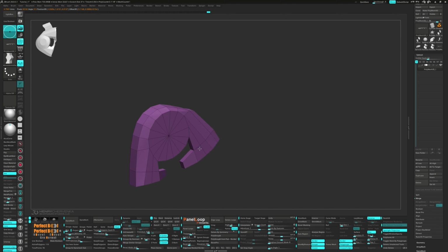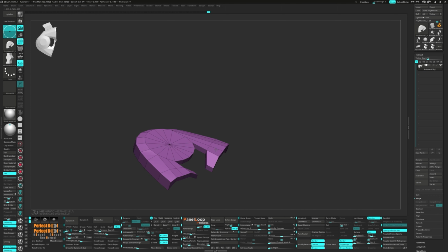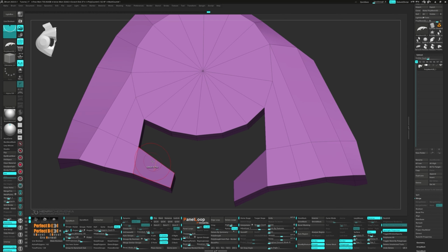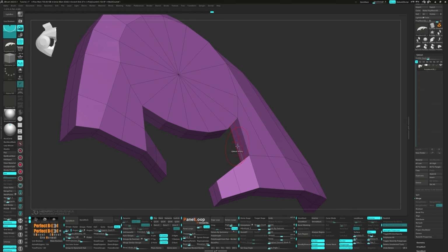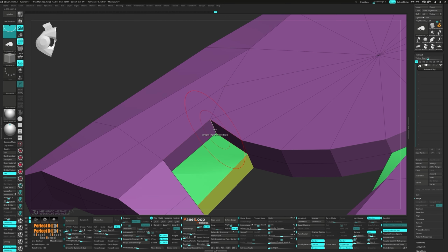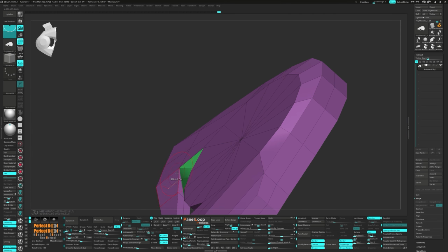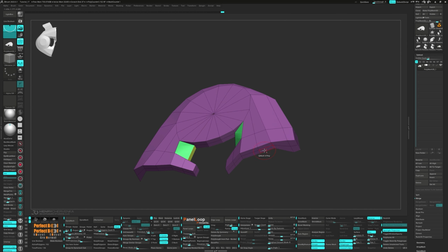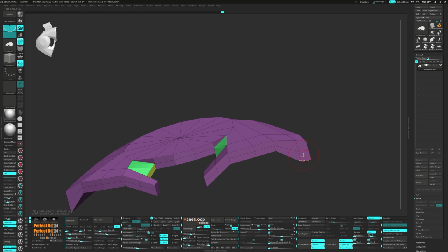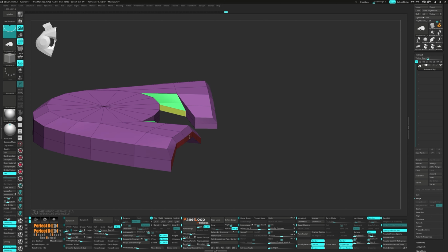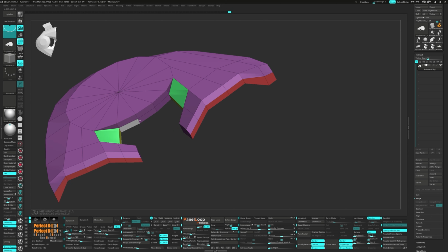But remember, the resolution you set before turning on Shadowbox influences how detailed your shadow projections will be. Now if you're just starting and you want to create a completely new shape, you're still going to need an object to start from. I suggest going for a simple primitive like the Polymesh 3D star just to get the ball rolling. After it's loaded, you can clear the converted mask from the Shadowbox walls and start creating your shape. And here's where the fun part begins. You get to use all the standard mask brushes to edit your shadow and bring your vision to life.